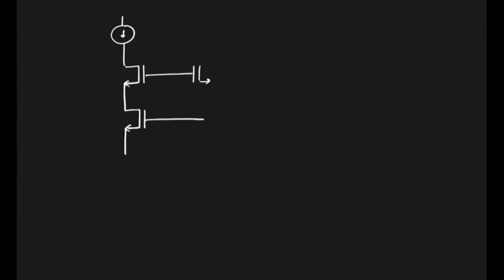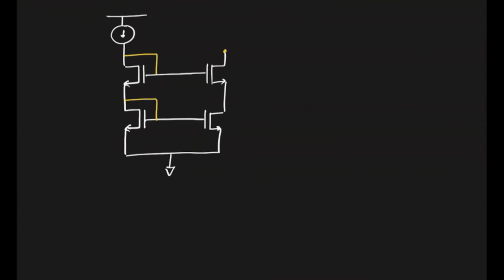Last lecture we talked about the cascode current mirror, and one of its limitations was... let me draw the cascode current mirror. What was the issue with this current mirror or current source? One issue we talked about last time was that the output voltage V out cannot be low. It's a large number, VT plus 2 VDsat. That could be a problem if you're trying to do a low voltage circuit, which is specifically 1 volt or 1.2 volts. This is VDD.